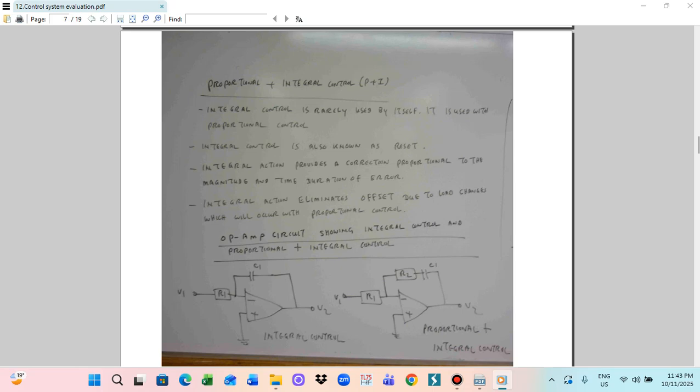So in this case, we can draw the electrical diagram. Electrically, we can draw the integrated and the proportional control. Normally, for the proportional control, you can draw the electrical diagram. There are two resistors for the operational amplifier, so the feedback resistor R2 provides the gain. Similarly, we can utilize it for the integrated control system. Instead of the resistor R2, we can put the capacitor. So in time, you can change it to the integrated control.